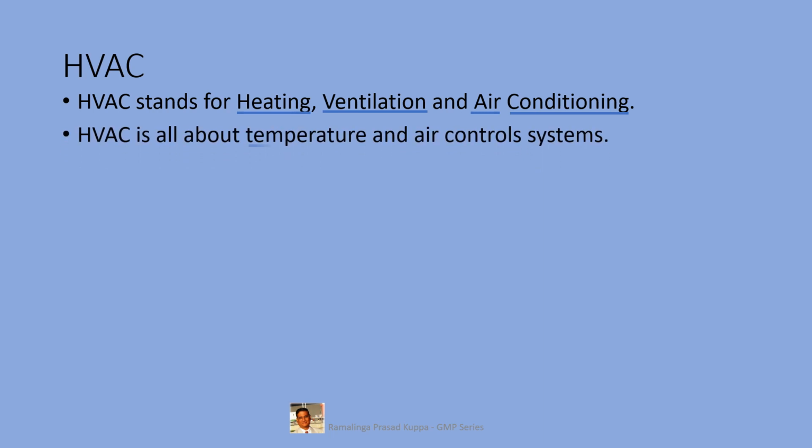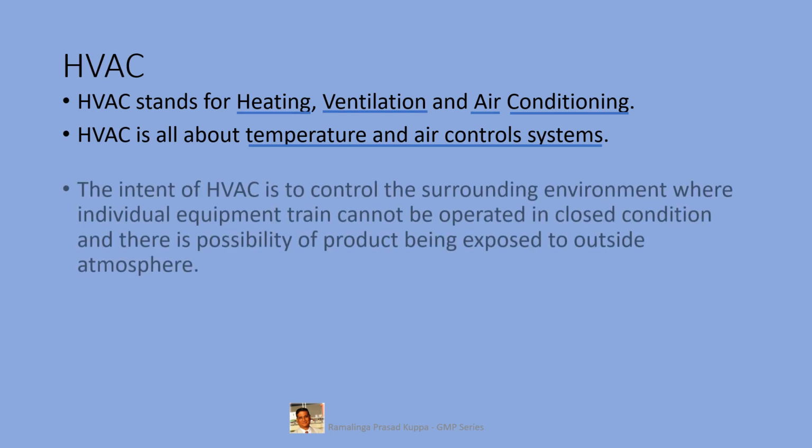HVAC is all about temperature and air control system. HVAC is all about handling of air circulation and control of temperature in closed rooms. Such closed rooms are called clean rooms. These rooms are classified according to the product requirements. Common classification is 100,000 classification for non-sterile products. Tighter classifications like 10,000, 1,000 and 100 may be required for aseptic sterile conditions.